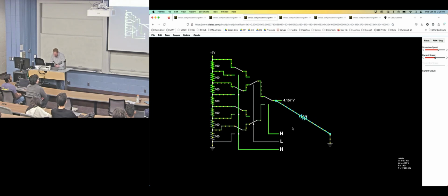The actual node is there. Aha, I've corrupted that voltage. So here I'm going to unconnect it from ground. Now no current can flow here. It's back up to 5 volts. I'll put it back on here. Now there's a path for current, and I've corrupted the output. Yeah? Couldn't you just put an amplifier there? Yep. Go put that voltage follower on there. Take care of it.